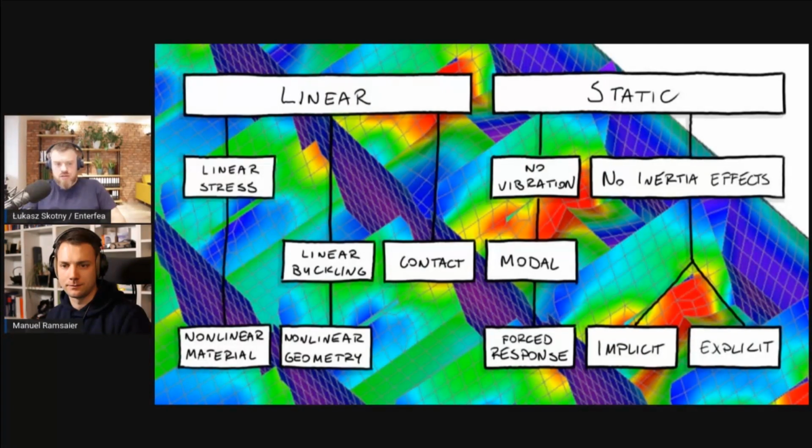So nonlinear geometry is the effect that makes this happen, because linear geometry would treat the string as a beam. It doesn't see that as the string deflects, it has to elongate, and this elongation is not for free. You actually generate tensile force by elongating the string.